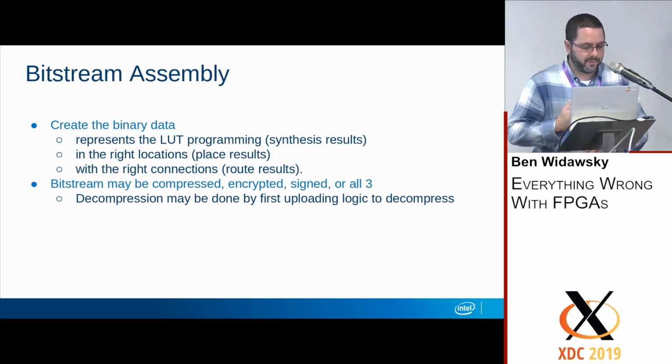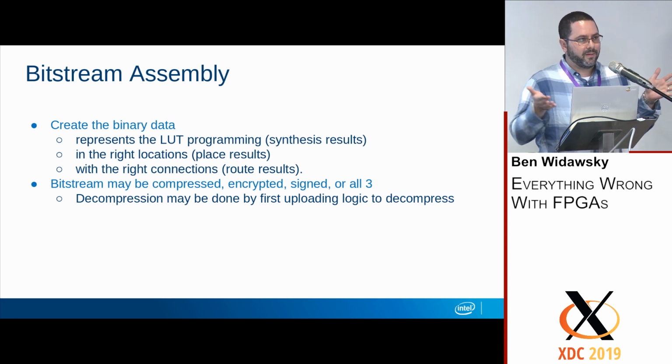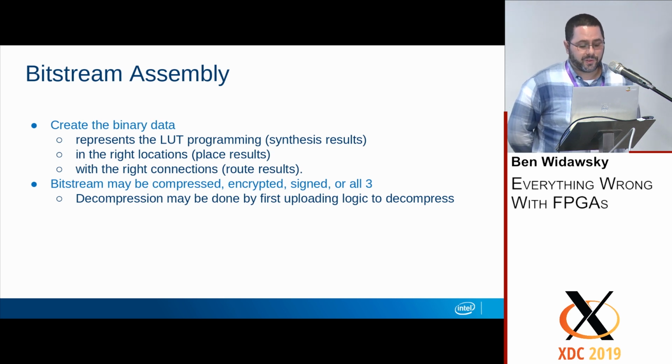Bitstream assembly is really straightforward, actually. It's what you'd expect. If you know what the LUT programming is and how to program the actual routing in the fabric, some bits go in some part representing the LUT, some bits go in the routing information, and you're good to go. There are some special cases.